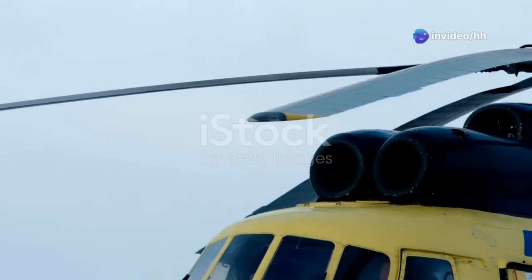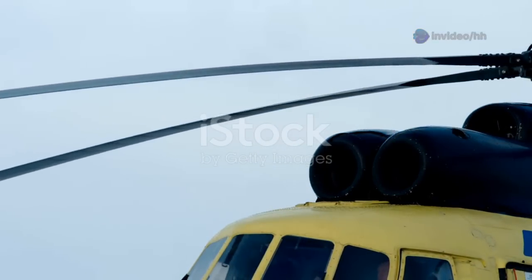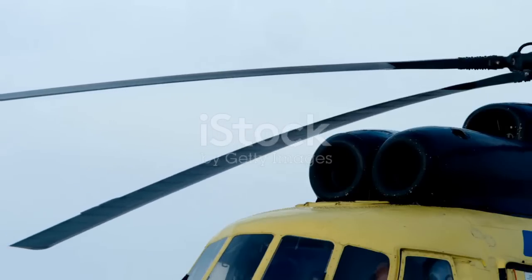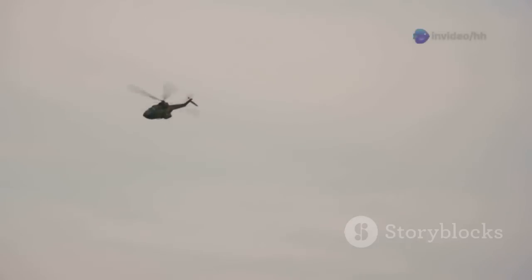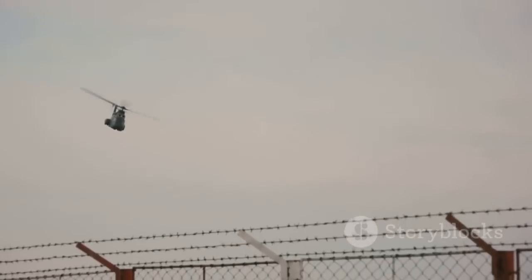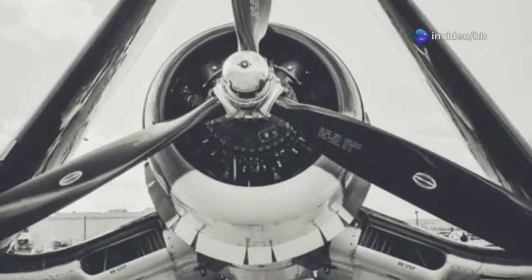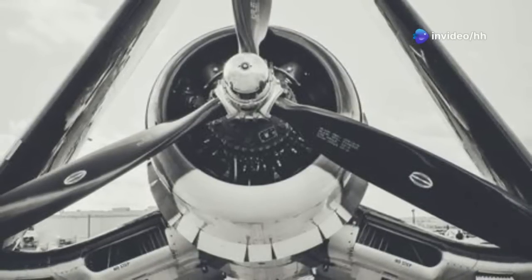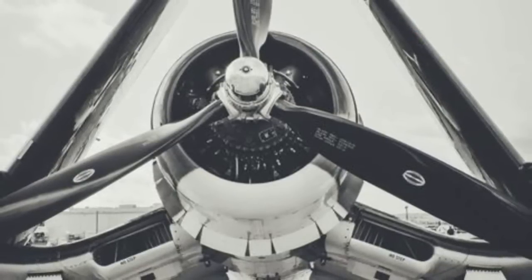Blade twist compensates for this difference in speed by reducing the angle of attack, the angle at which the airfoil meets the oncoming air, at the tips. This reduction helps to balance the lift generated along the blade. At the same time, the angle of attack is increased near the hub, where the blades move slower. This increase ensures that the inner sections of the blades also contribute effectively to the overall lift. By carefully designing the twist, engineers can ensure that the lift is more evenly distributed across the entire rotor disc. This even distribution is key to achieving a balanced and stable flight.